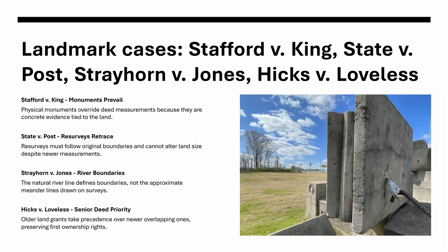The fourth case we studied was Hicks v. Lovelace, decided in 1986. This case involved overlapping deeds. Two grants covered the same land, and the question posed to the court was which deed should prevail, the older or the newer. The court ruled that the senior deed prevails. First in time is first in right. If two grants overlap, the older one takes priority. The junior deed is limited to whatever land remains outside of the senior grant.